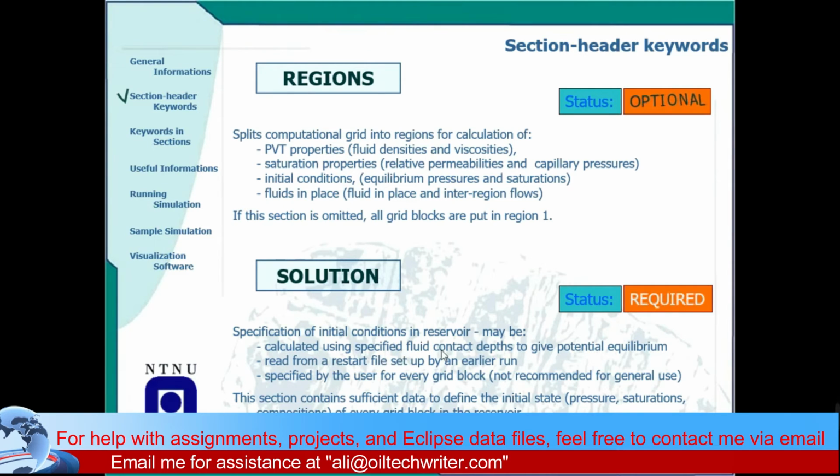The SOLUTION section is required because the initial conditions may be needed, calculated using specified fluid contact depth. The initial conditions are given in the solution, like what the initial pressure of the reservoir is, the initial temperature, how much the initial oil saturation and gas saturation are, or whatever. So here you can see pressure, saturation, and initial composition that you have to define.